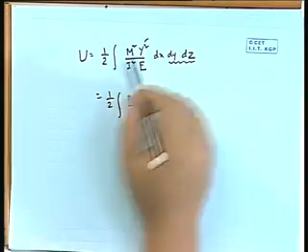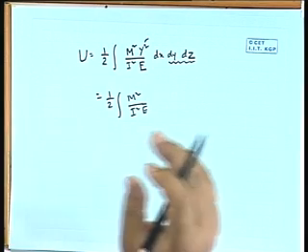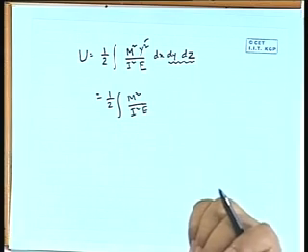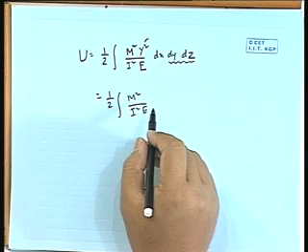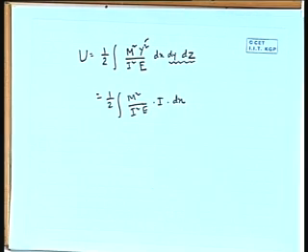So, if we integrate about dy dz, about y z, here y square will be coming into the equation. So, dy dz, if we write it is dA. So, integration y square dA is what? Second moment of area. So, we can write this one as I dx, right.